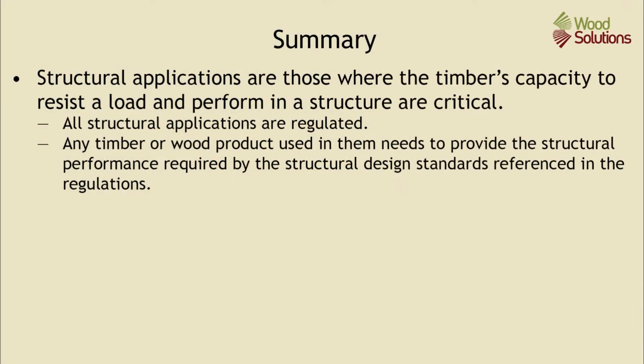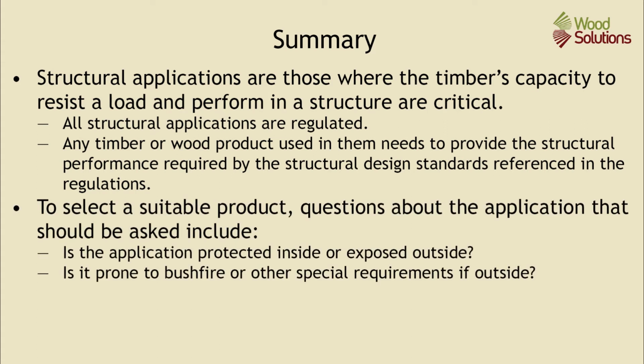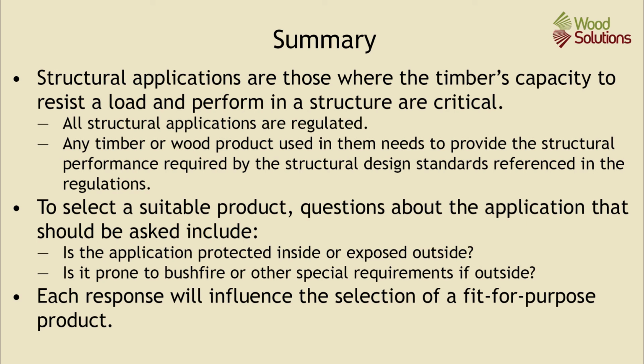In summary, structural applications are those where the timber's capacity to resist a load and perform in structure are critical. All structural applications are regulated, and any timber or wood product used in them needs to provide the structural performance required by the structural design standards referenced in the regulations. To select a suitable product, questions about the application that should be asked include: is the application protected inside or exposed outside? Is it prone to bushfire or other special requirements if outside? Each response will influence the selection of a fit-for-purpose product.